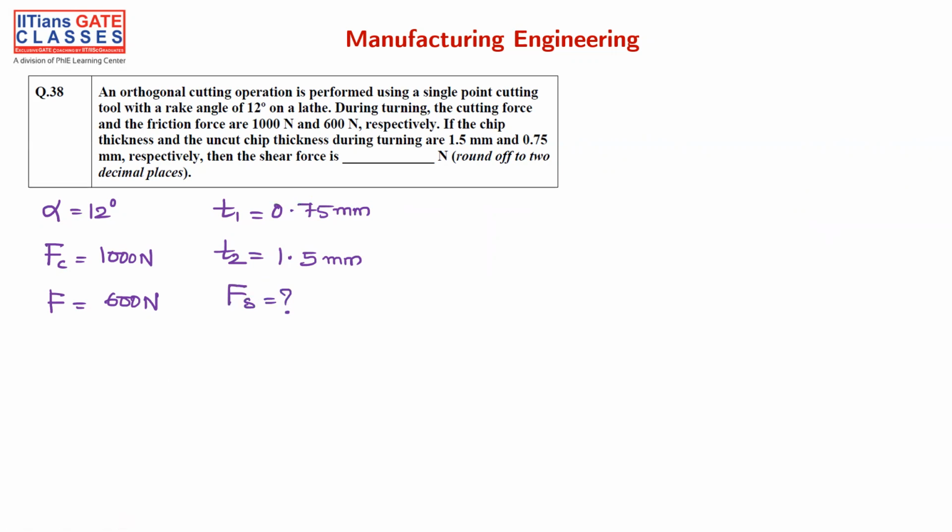So obviously, as we are dealing with the cutting forces, we'll be dealing with the merchant circle diagram, right? So let's use the merchant circle diagram to find out the shear force. Okay, let's draw the merchant circle diagram. So this is your circle, and let me draw. This is your perpendicular planes, right?